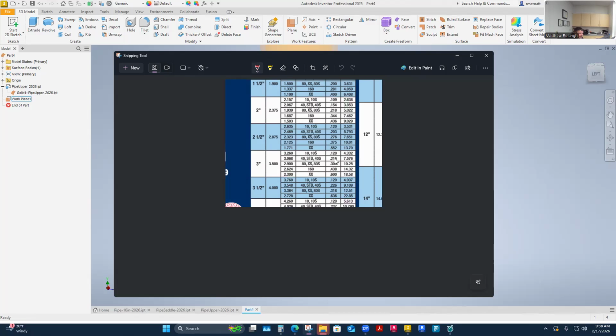And then I'm going to stop and evaluate and say, once I get that diameter of the ID, does it fit my 2 inch and my 2.5 inch pipe? Because they have to work together. And it might be that I have to get creative and order a different wall schedule thickness in one of them. However, if I do that, I have to know that I'm supporting the right load and I'm not minimizing how much this pipe support can hold by dropping away from a standard pipe, and maybe creating a part that would have to be machined or whatever.